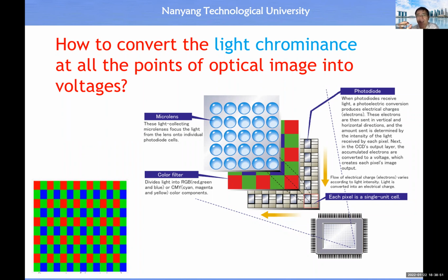How to separate red color? Then we have a red color filter. How to separate green color, we have a green color filter. How to separate blue color, then we have a blue color filter. Because the red color filter means what? Only the red component can pass through, right? Green color filter means what? Green component will pass through, right? So then in this case, one point must make use of 4 sensing elements, right? Instead of 1, because we must separately consider the value for the red component, the value for the blue component, the value for the green component, all right?